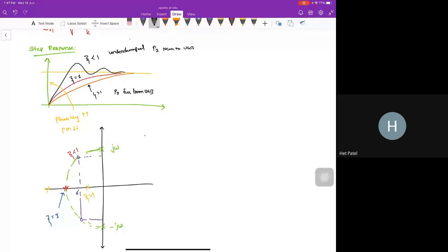Actually it adds more phase in the system, we will see that, don't worry about it. It adds more phase into the system, so the phase margin is very less, and we are getting a ringing in the output. If my pole is on the j omega axis, then our output will just oscillate, sustained oscillation we will get. So that kind of thing is there.